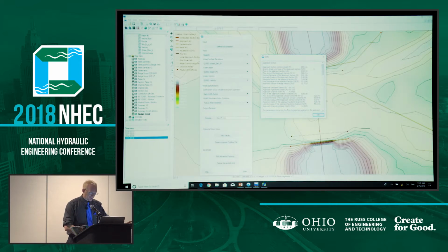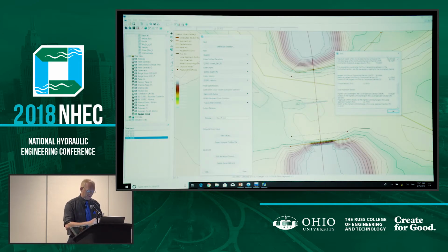And I'm going through this kind of quick, so I'm not necessarily putting it all together correctly. And this just gives you the hydraulic information of the approach section, the contracted section, or the scour section, as I've been calling it, the local approach section. When SMS does this, it's going to generate a few arcs, and one of them is approach section and streamlines, and it gives you information for all of these parts that it's extracting information out of this 2D model so we can put it into Hydraulic Toolbox and leave less information for you guys to go out and figure out where it is in the model and bring it over.